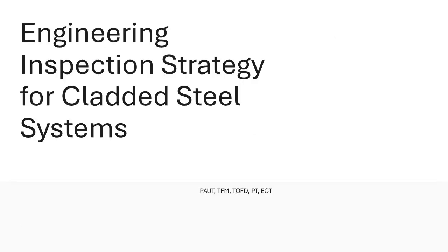Introduction to NDT challenges in stainless steel cladded carbon steel: inspection challenges due to dissimilar metal cladding, limitations of conventional ultrasonic testing, primary inspection method phased array ultrasonic testing, PAUT applications, disbonding, welds, and corrosion mapping, advanced PAUT imaging, total focusing method, TFM, time of flight diffraction, TOFD, for weld defect sizing, surface inspection using liquid penetrant testing, PT, eddy current testing, ECT, for near-surface evaluation, recommended NDT strategy and key engineering considerations.